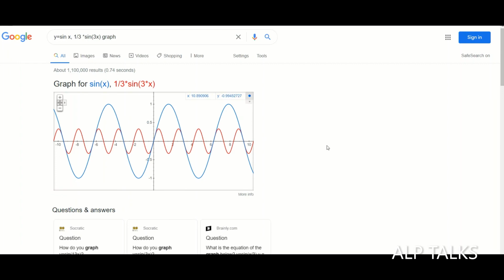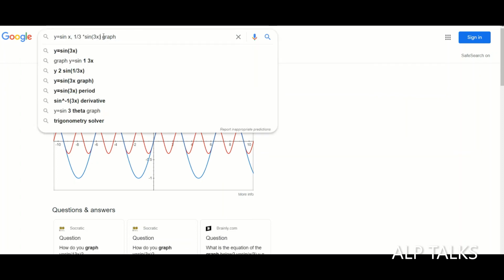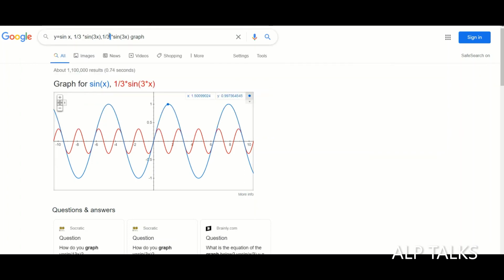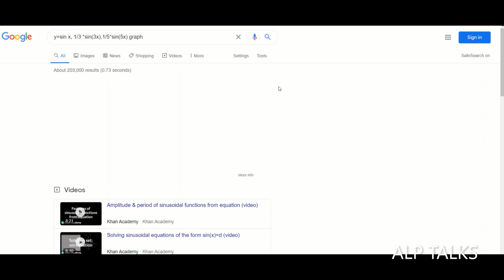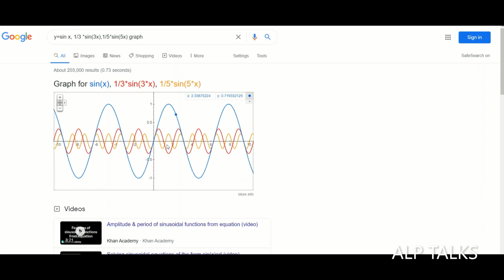The waveform will be like this. Up to here we have one fundamental waveform, and within that we have three cycles of the third harmonic component. Similarly, I'm simulating odd harmonics now. The fifth harmonic will be 5 times the fundamental frequency. You can see it here: within the first half we have 5 cycles of the fifth harmonic.